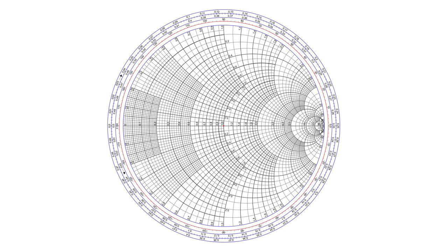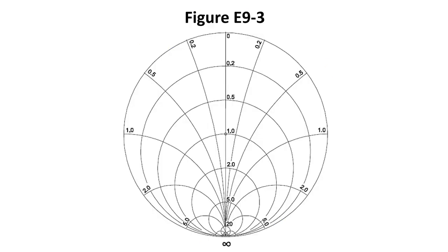Ham Math Guy said it is possible to find Smith charts with 50 ohm prime center. That way there's no need to normalize. I have not seen one. There's also an X and a Y version of a Smith chart. I didn't really look to see what the difference was, but I'm thinking this one is going to be an X version, and the one that we looked at from the question pool earlier that didn't have many circles on it, I'm thinking it was a Y version because the resistance was going up and down, and this one it's going horizontal. Good chance.